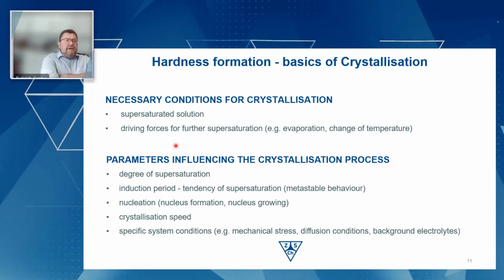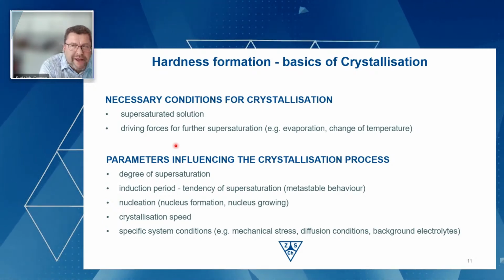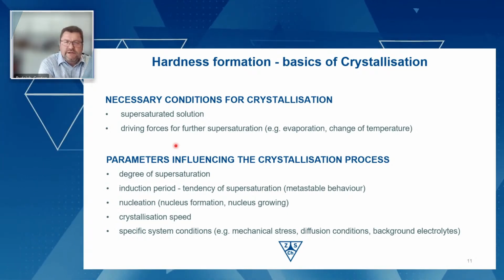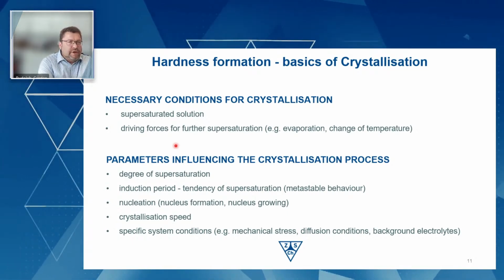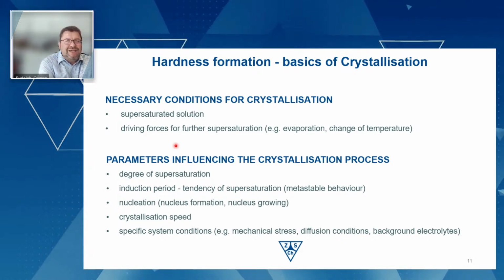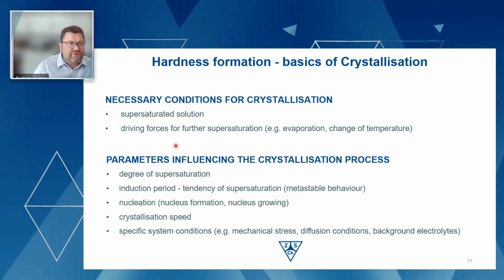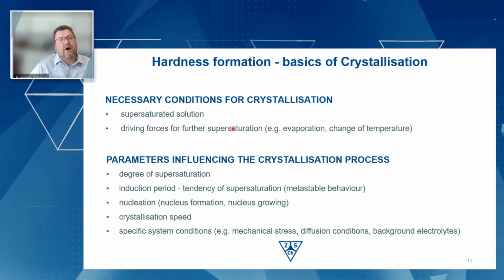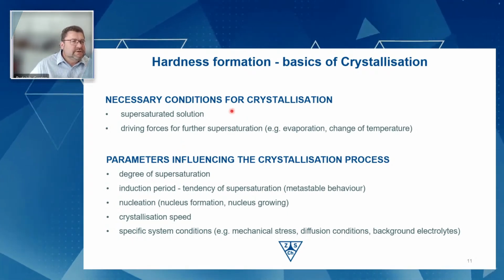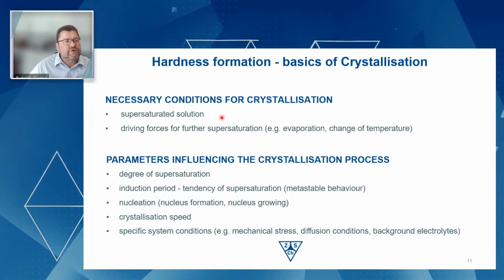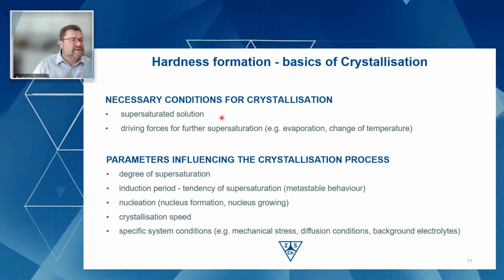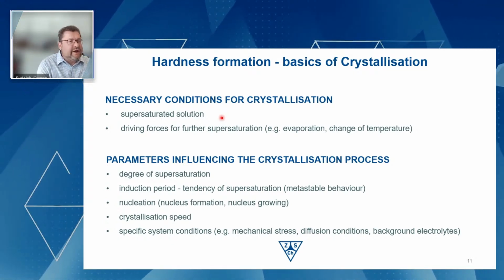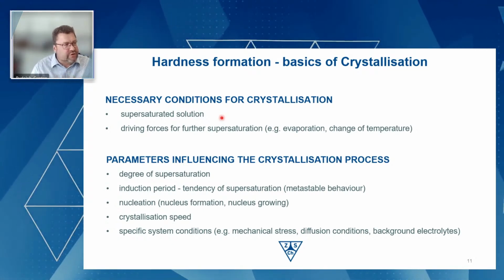So if we speak about hardness formation or about this chalk formation, everything is about crystallization, because crystallization is the key to form these encrustations. So it makes sense to understand how this crystallization works. The necessary condition for crystallization is any supersaturation. So crystallization takes place on areas where we have supersaturation.